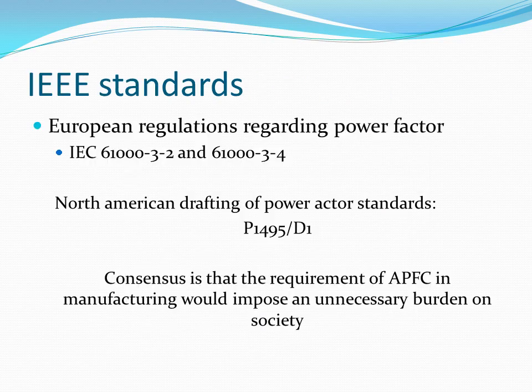Due to many products having a poor power factor, as we have seen in earlier sections of this video, this has caused problems for the utilities, and in Europe it has prompted the passing of 2 regulations. These 2 standards are European regulations that require all electrical equipment connected to a low voltage distribution system to minimize current harmonics and maximize power factor.